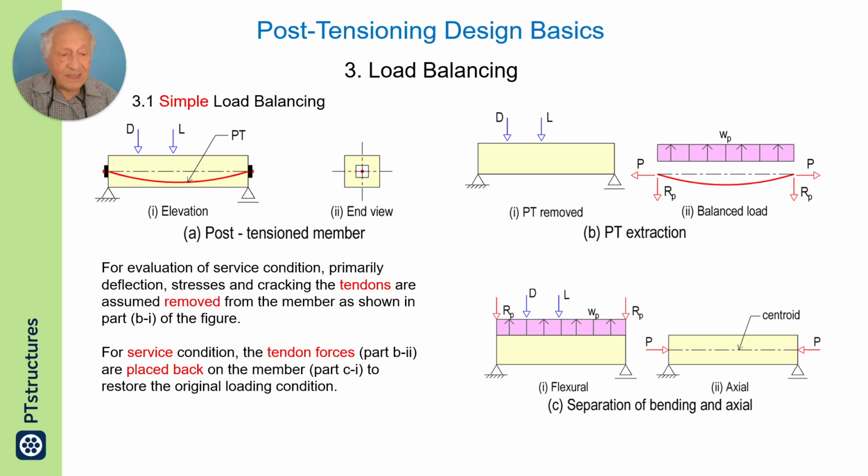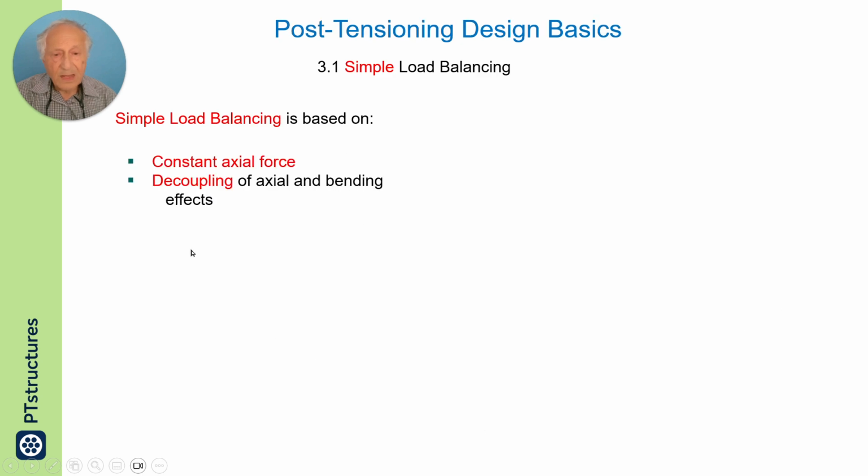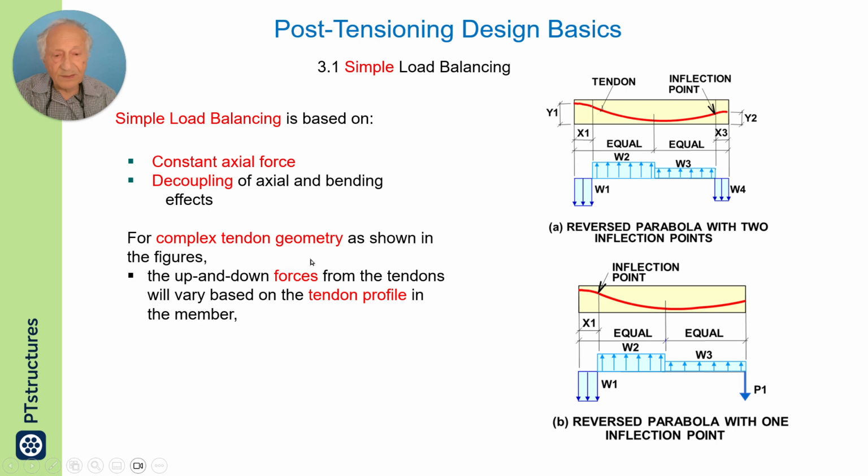So it was a method to which the engineers were familiar, and it resulted in a widespread use of the technology, but it was based on the fact that the separation resulted in the diagram as I show on the bottom right, which is uniform pre-compression. Uniform pre-compression as shown at bottom left. So simple load balancing is based on constant force and decoupling of axial and bending effects.